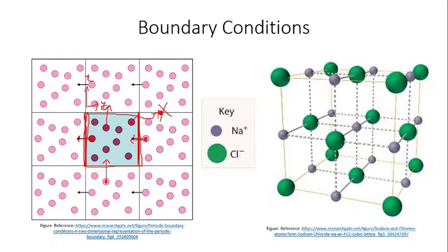After that comes the shrink wrap. Shrink wrap means the position of the face is set so as to encompass the atoms in that dimension, no matter how far they move. That means suppose this atom in one time step goes here. Unlike the fixed boundary, in the shrink wrap boundary, this boundary will move and come here, and this atom will not be deleted.